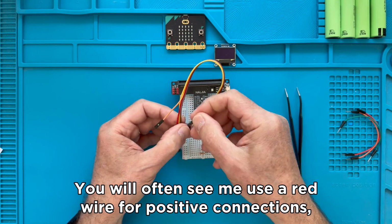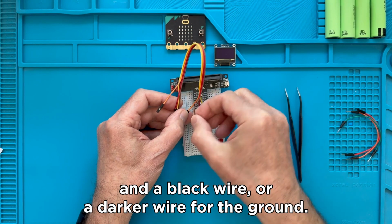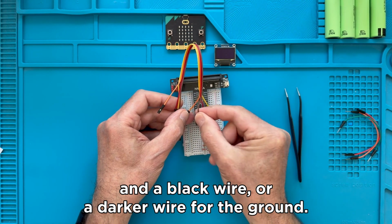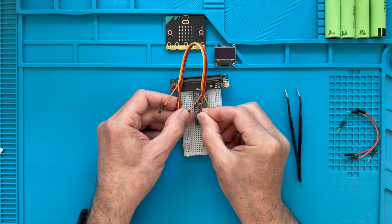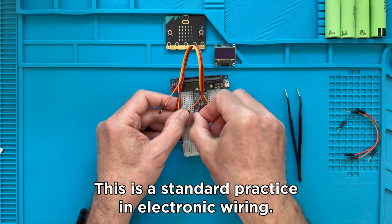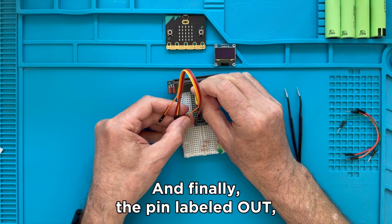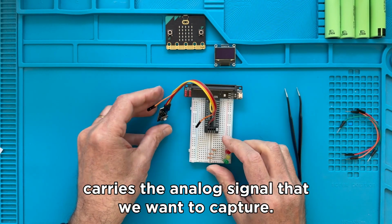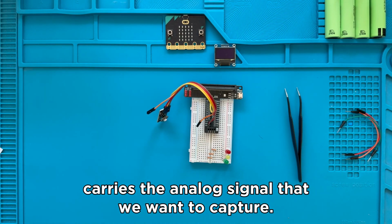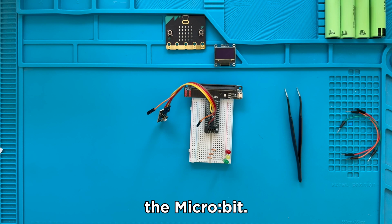You will often see me use a red wire for positive connections and a black wire or a darker wire for the ground. This is a standard practice in electronic wiring. And finally, the pin labeled out carries the analog signal that we want to capture. So we will connect that to, for instance, pin 0 on the microbit.